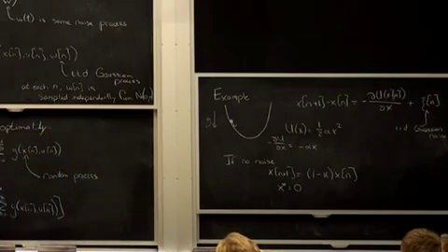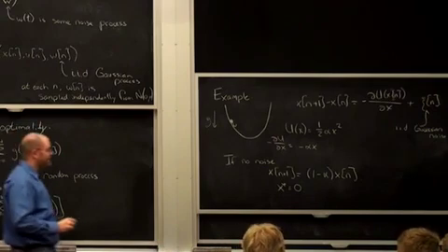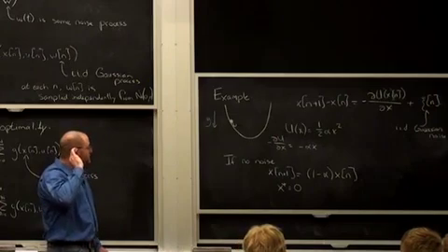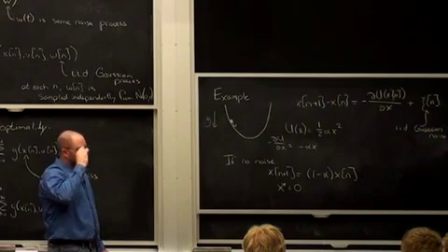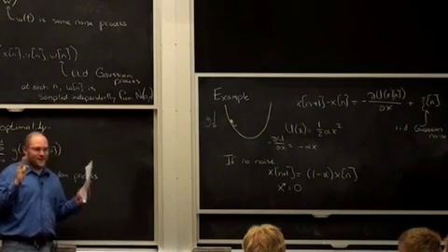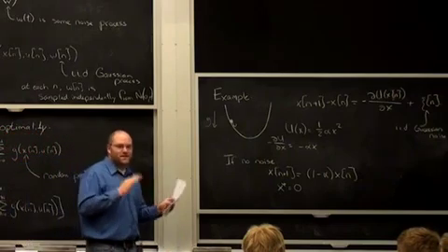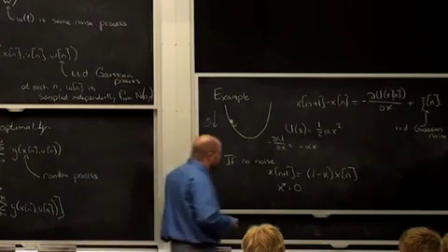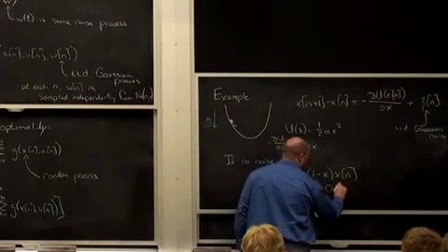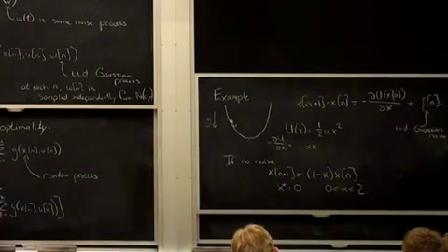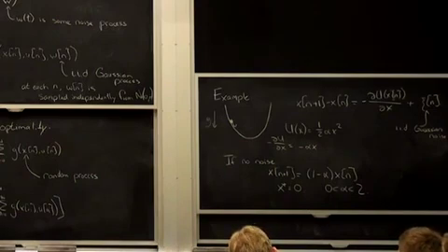And when is it stable? Discrete time linear system. Certainly when alpha is between 0 and 1, but there's more than that. Yeah. Positive? No, you're thinking too continuous time. In discrete time, your bounds on your eigenvalues are that the absolute value has to be less than 1, right? Which I think in this case means alpha's got to be between 0 and 2, yeah? Everybody okay with that? That wasn't supposed to be the big insight for the lecture, but.